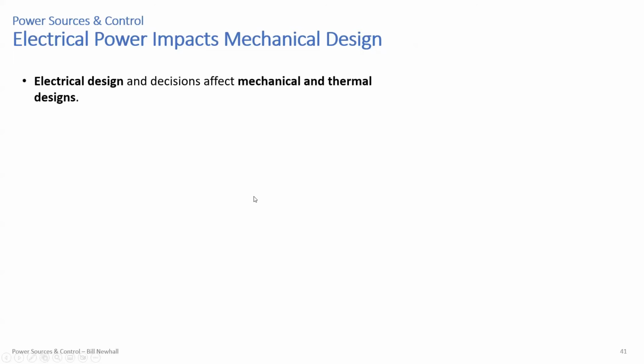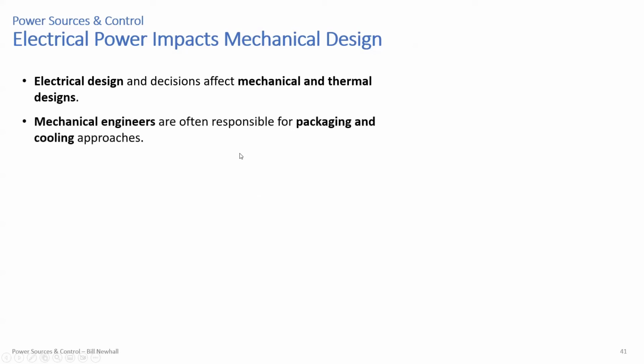Electrical power impacts on mechanical design. So, right, you're mostly mechanical engineers. You're learning about MOSFETs at this point. And so some of these design selections when electrical engineers or you are designing MOSFET circuits impact the mechanical design and the thermal design. Okay, so that's why it's useful knowing some of these more detailed topics because they can affect your life and your work. So mechanical engineers are often responsible for the packaging of a product, and this includes the cooling approaches.